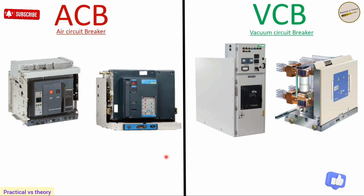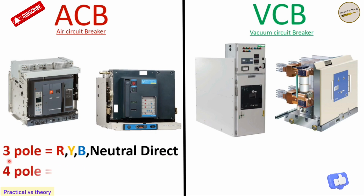So, next comes your 3-pole and 4-pole. Look, you should know about neutral direct. Why is it called neutral direct? Suppose I have a breaker. It has R phase, Y phase, and B phase. For example, I have a TP, a triple pole MCB, okay? I don't have a neutral in it. So, if I have a triple pole MCB with a neutral, I'll use it directly, okay? So, that means I'll use the neutral directly.